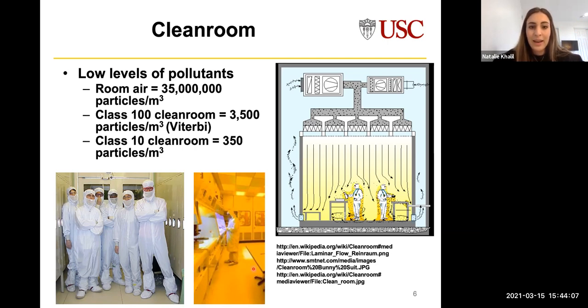And the last feature of a clean room is this yellowish hue. We're working with light-sensitive materials, materials that are specifically sensitive to UV light. And regular fluorescent lamps actually do emit some light in the UV spectrum. And so these have to be filtered out. So we're filtering out lower wavelength light and we're left with this unpleasant yellowish color.